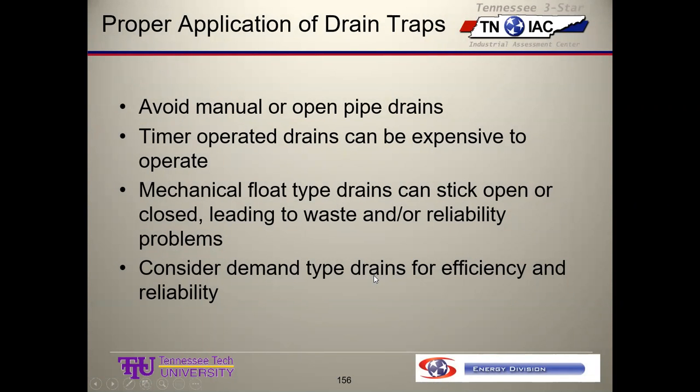Okay, so avoid manual or open pipe drains. Some people will do this because you've got some guy you're paying $15, $18 an hour, and you tell him every day, I want you to walk around this plant and make sure there's no moisture building up in these tanks. Well, for about the first month he does it, and then you know what he does? He comes and cracks the valve just a little bit open. So they just sit there and psst. He doesn't have to walk around, right? There's no moisture in that tank. But now he's got 15 leaks. He's done it on purpose because he gets tired of walking around there. It's cold outside, I have to walk over to that other building. I'll just crack that valve open, nobody ever goes over there. Nobody will ever know. That's what happens.